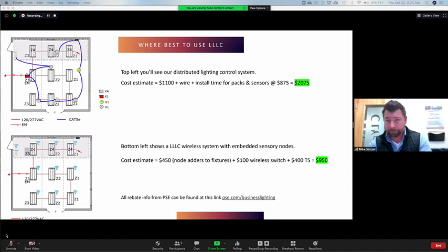And then typically the rest of them would just get silent nodes, which allow for luminaire light level control and communication between all the rest of the lights and the rest of the system, but they don't have sensors in them. So they're not individually fluctuating daylight controls and light harvesting. They would get their information from the light fixture next to them. This reduces cost. It also reduces lights along the same line being at different intensities.